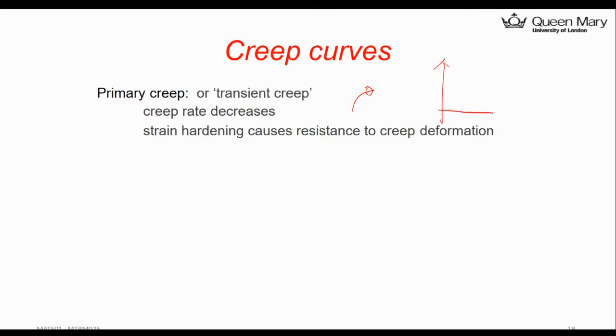Strain hardening, basically, if you have stress and strain, and you go through the linear region and then go up and keep hardening. Okay, that kind of behavior will correlate to this creep curve, and then you will have a linear plateau. They are plotting different things, but here it is caused by this strain hardening effect.